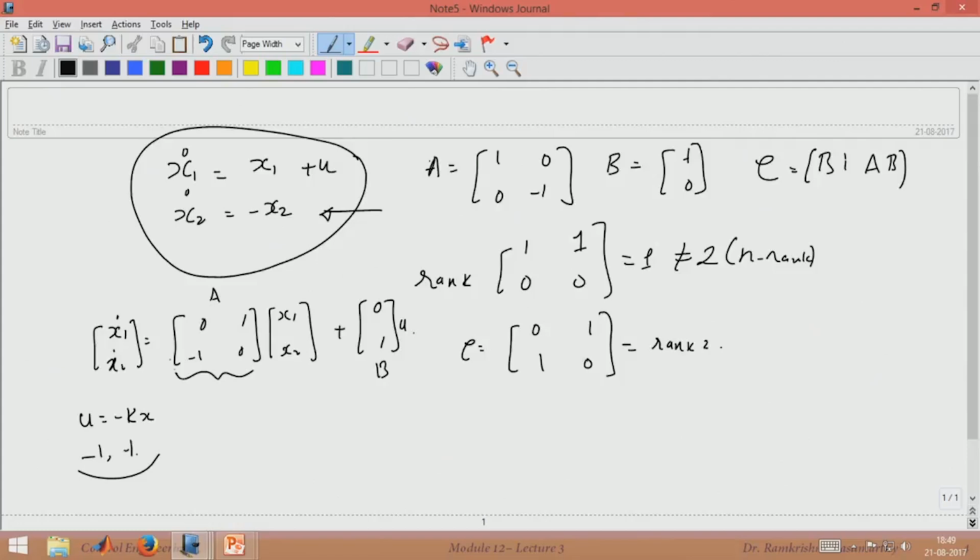Well, where are the poles of the open loop system? You look at the solution of the characteristic equation sI minus A equal to 0, and you find that the poles or the eigenvalues are just at plus minus j omega. Now, can I choose u equal to minus kx, or, in this case, since this is a system of 2 variables, k1, k2 times x1, x2, such that this holds.